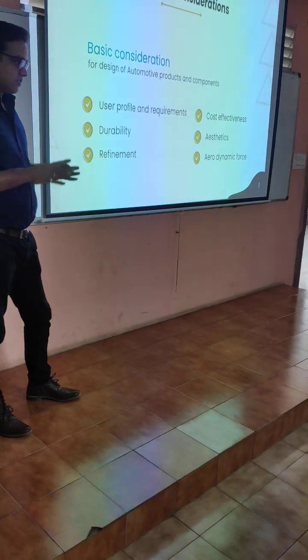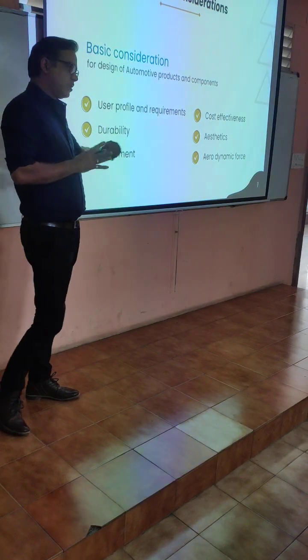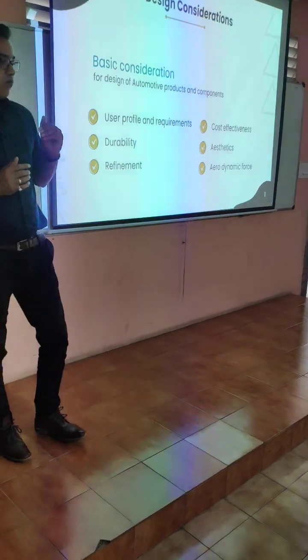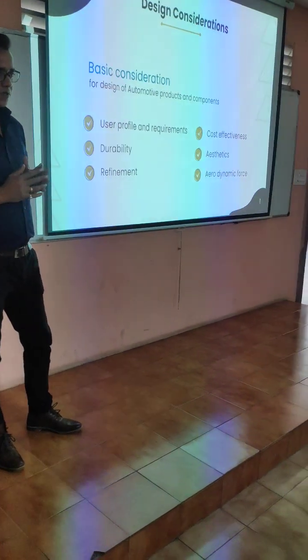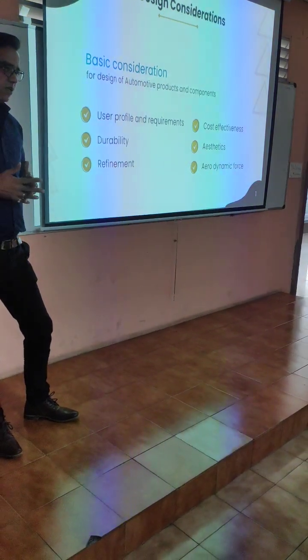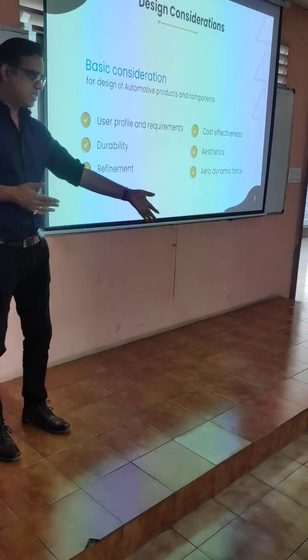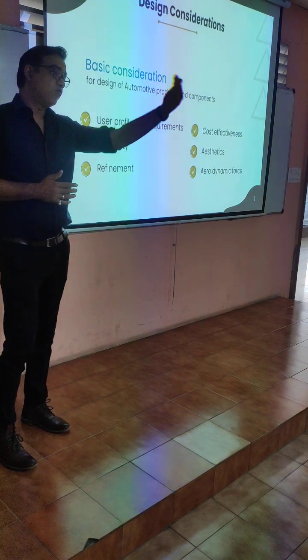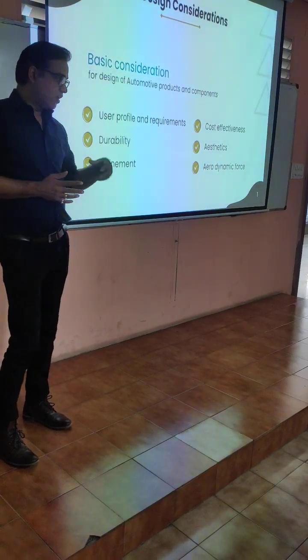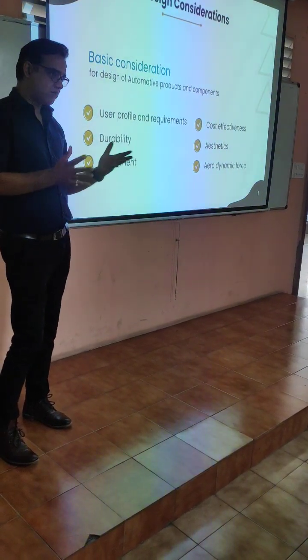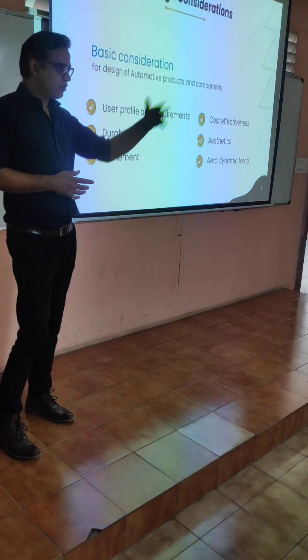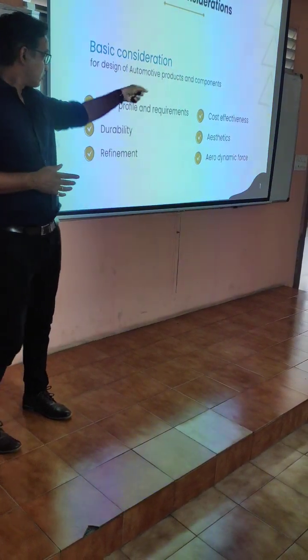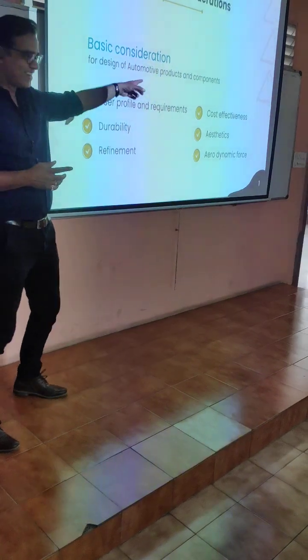Most important consideration when you are doing durability is to design it for more than your requirement. Anything you do for just the requirement will fail very soon. So you do it more than the required. So 140%, typical industry standard. If you are a German, you will do 300%. But then the cost effectiveness problem is there, right?